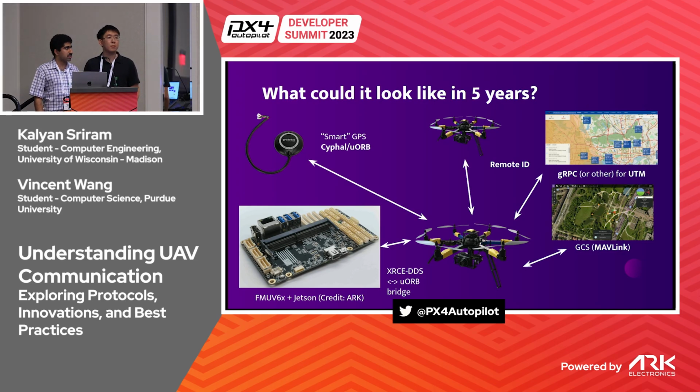Smart ARM peripherals running PX4's DroneCAN node and ArduPilot's AP Periph, which provide DroneCAN firmware, will become cheaper and more intelligent as they mature. DroneCAN may continue to be used for many of these devices, but Cyphal is also maturing, and as the barrier to entry reduces, it might start to replace DroneCAN. Looking further into the future, we might start to see redundant and distributed avionics as PX4 runs different modules on different hardware nodes using CAN-FD or even Ethernet as a backbone.